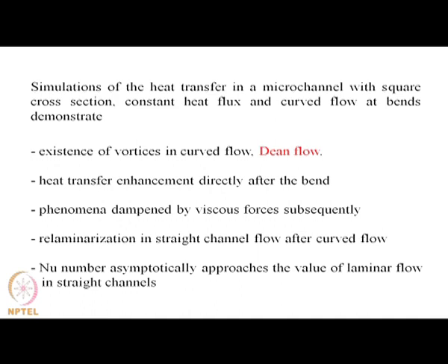with constant heat flux and with curved flow at bends, they demonstrate certain interesting trends which we have already discussed, but I am summarizing it over here. So, if you have flow in a microchannel under constant heat flux condition, and there are bends present in the path, and there is a curved flow, what you see first is the existence of vortices at the bends, which is called Dean flow. So, the existence of Dean flow can be seen from the numerical simulations.